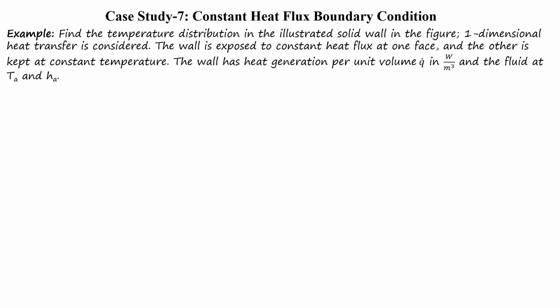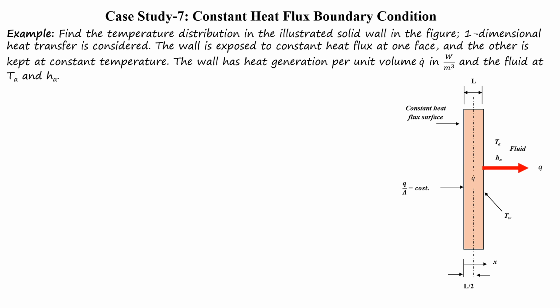Let us talk about a boundary condition where a constant heat flux is directed to one side of a wall which experiences a heat generation, and the other face or other side of the wall is exposed to convection, where a fluid is passing with a temperature T ambient and a heat transfer coefficient of h sub a.